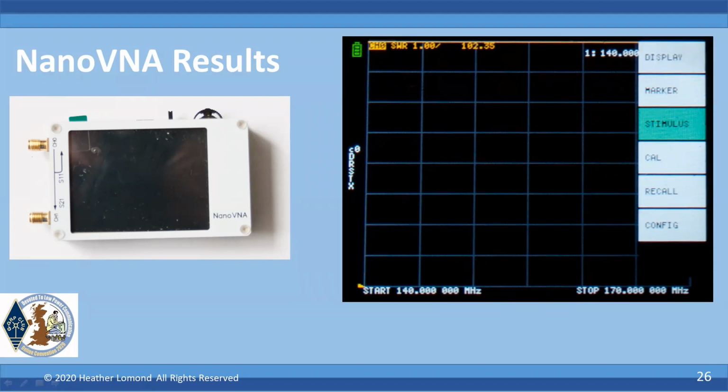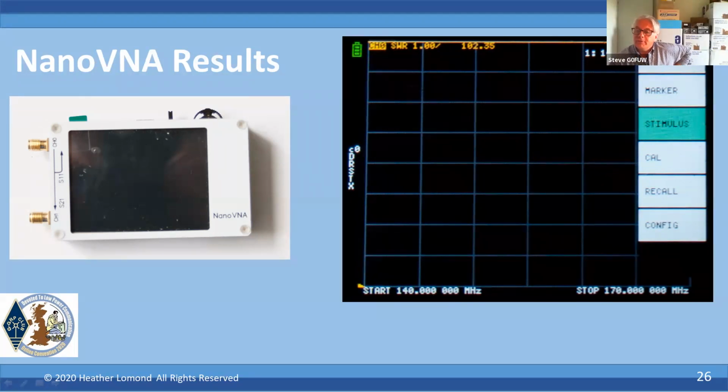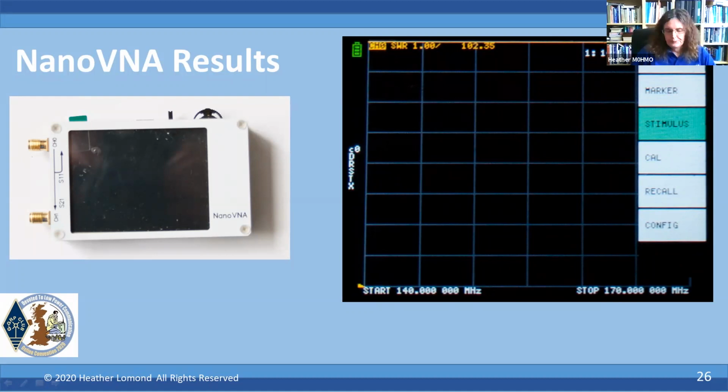One from Tristan. I'm tempted to say with a pair of pliers, but the question is, do you know if you need to shorten a dipole from the results of the analyzer? Okay, so if your dipole, now I've got to get this the right way around. If its minimum SWR frequency is too low, then the dipole is too big and you need to shorten it.